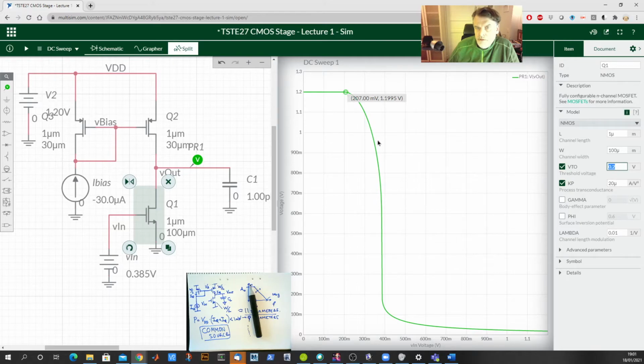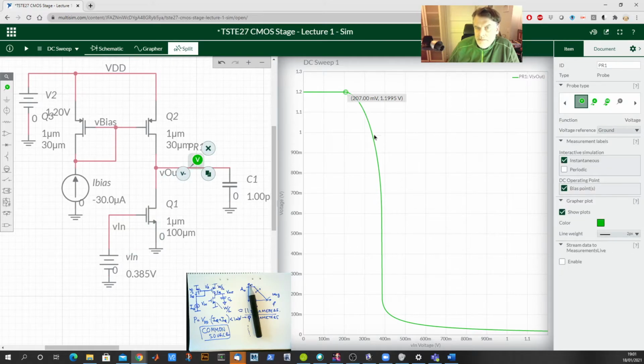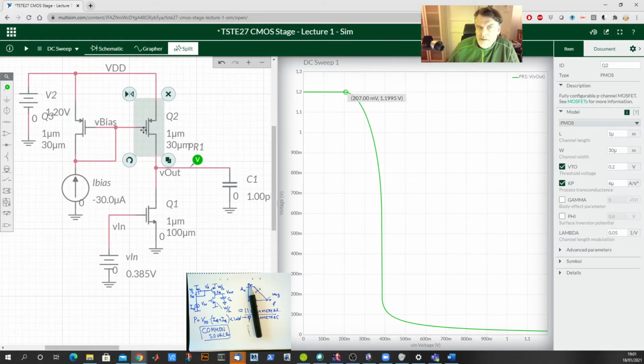So now we turn on the transistor, but the output voltage is really high, and these guys do not seem to have a good gain, even though they potentially should. But that's because these transistors operate now in the linear region, so they act like a resistor rather than a current source, until a point when I have reduced the output voltage so much that these guys come back into the saturation region, and that's when I enter this phase here.